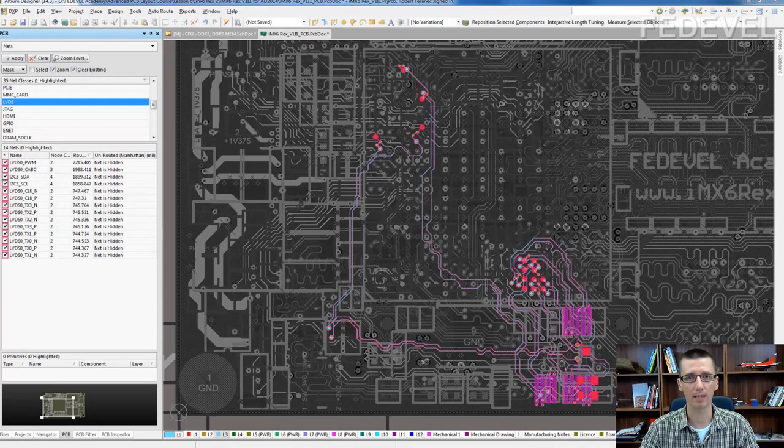Now let's speak about the length matching of the other interfaces: LVDS, HDMI, Ethernet, and these kinds of interfaces. How do you know what the length matching requirements for them are? You can read it in the design guide. Sometimes. Not every design guide will describe the length matching requirements for LVDS, for HDMI, and these kinds of interfaces.